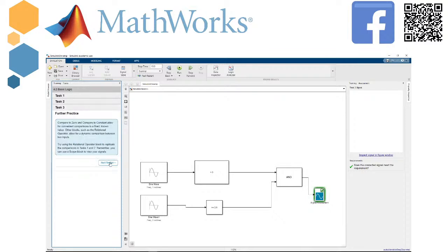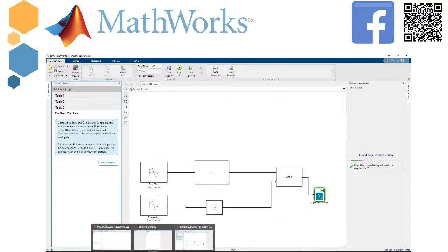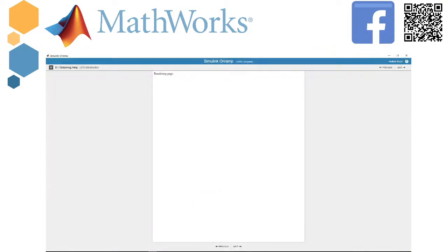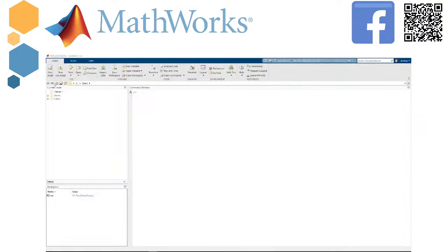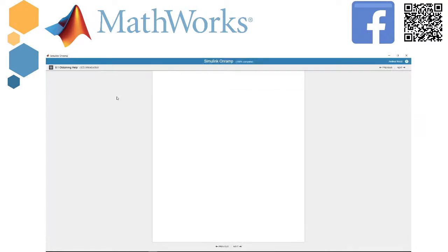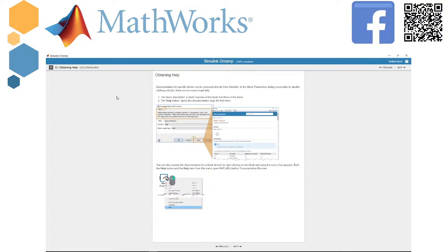The solution of OR is so we create a sort of code for if else. As you know, in MATLAB there is the if else condition, and we wrote it on Simulink as well. So add the logical statement replicated here. If something like that happens, we need to use mode 2, else mode 1. Okay, really easy. So we need to create a block which is called switch.